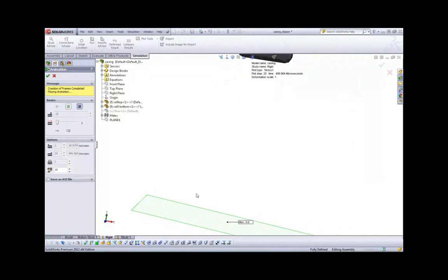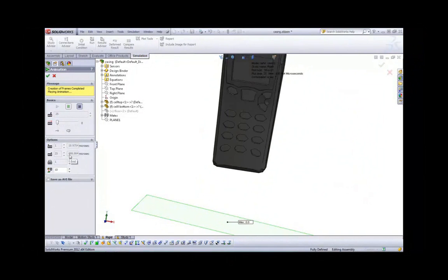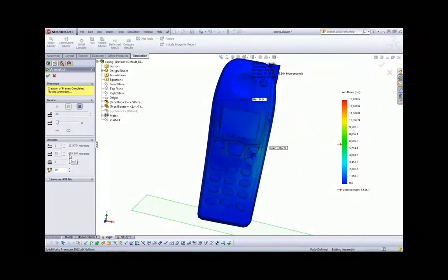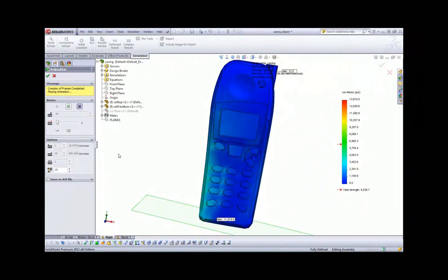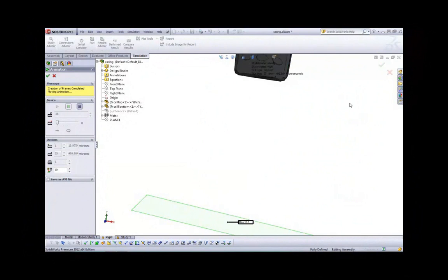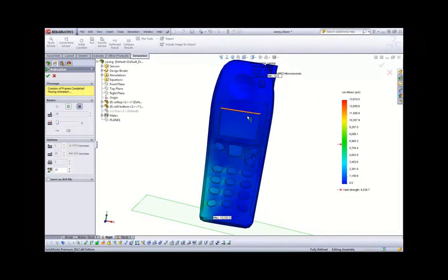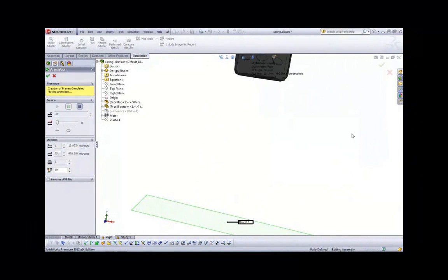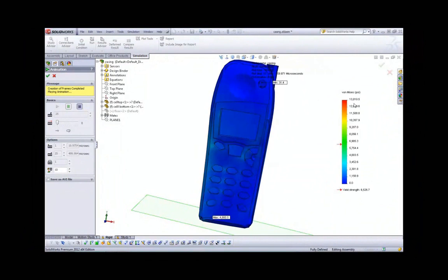Okay, so you can actually see the stresses propagating through the component. And this is up to 500 microseconds after impact. Again, I would probably want to do at least double this just to see exactly what's going to happen. Okay, we can see here that if I look to the right on my stress plot, we are past yield at some points, and we can see that the red is down here. And we can actually follow the max stress. It's always down here. So this is actually breaking. The acrylic is actually breaking. So from 6 feet, this thing does in fact break.